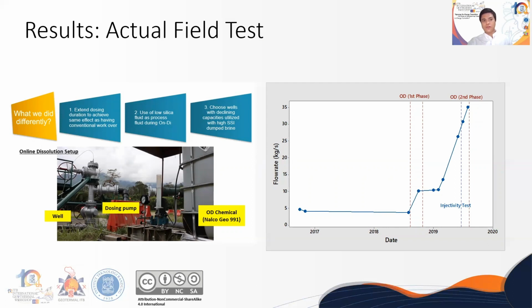This is also the original well capacity when the well was drilled. Aside from the flow rate measurement, ultrasonic thickness gauging was also conducted to ensure that the thinning rates during the actual run are within the acceptable limits.